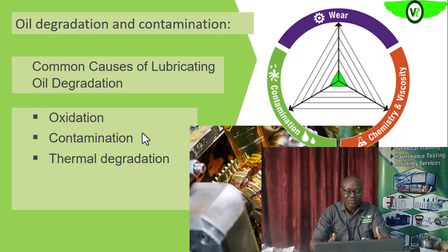All of those will be transferred to the oil, cause degradation of the oil, and then eventually affect the engine parts, which will also increase the thermal stress on those parts, because as the frictional forces are increasing, the temperature will also go up. So thermal degradation is one cause of lube oil degradation.